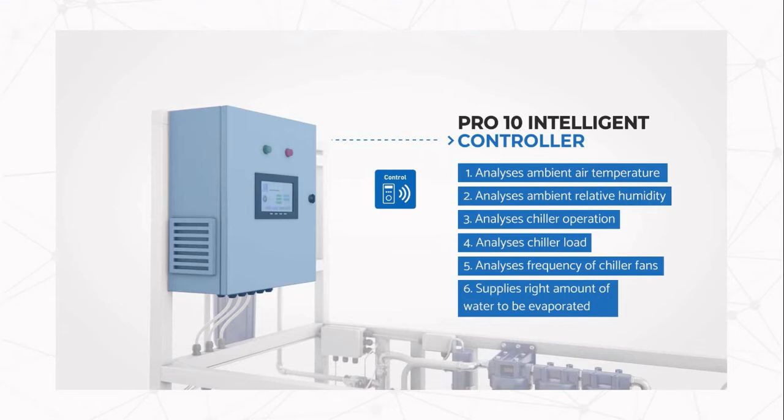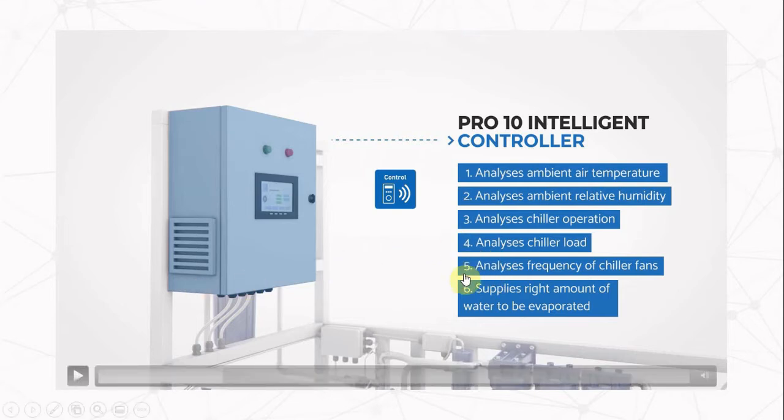Next, it is essential to receive a signal from the chiller fans. If your chiller has constant speed fans, the smart cooling device is customized for the specific airflow stated in the chiller specification sheet. In case of variable speed drive fans, we are able to get the signal from the chiller board to understand at which speed the fan is rotating.